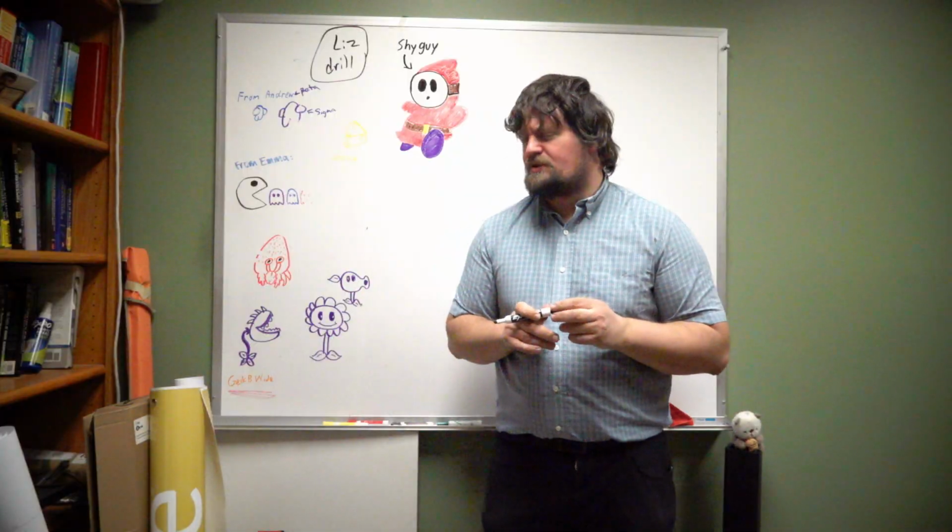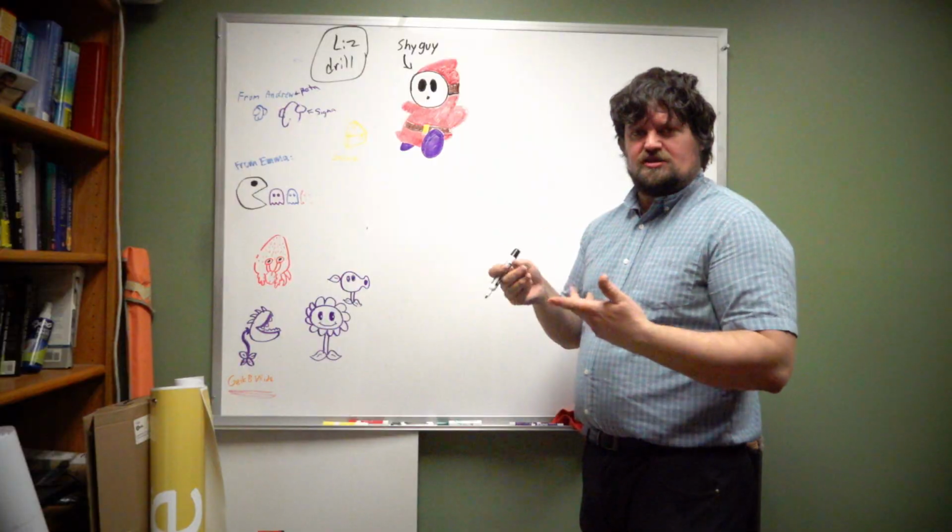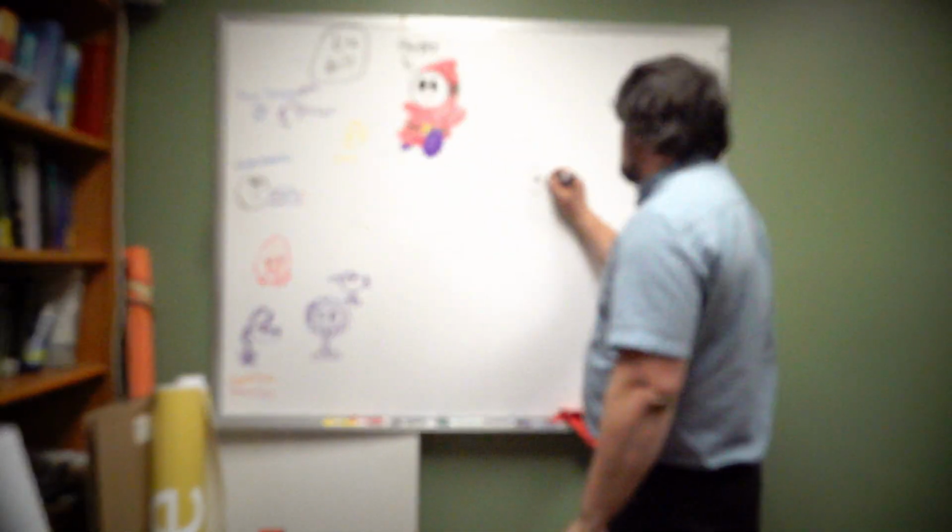When we're talking about bending moments, the way that they are created is through some kind of a shearing. So when we're looking at a bending moment being applied to an actual material, let's say we're going to apply this one in, and using the right hand rule, that's going to go into the board. So we'll draw it in that configuration. The other one will be here. This one here is coming out of the board, so we'll draw it in that configuration. This is the notation for coming out of the board. This is the notation for going into the board.